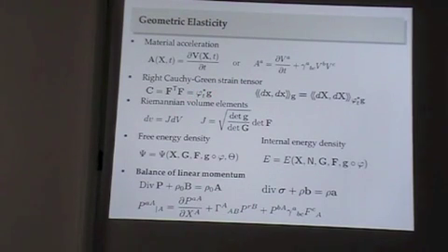I'm going to be working with incompressible materials to simplify kinematics. So J, or the Jacobian, tells you the relation between volume elements in the reference configuration and ambient space. And if you look at the classical formulations, they say J is the determinant of F, but that you have to modify when you have non-trivial geometries in the reference and ambient space manifolds.